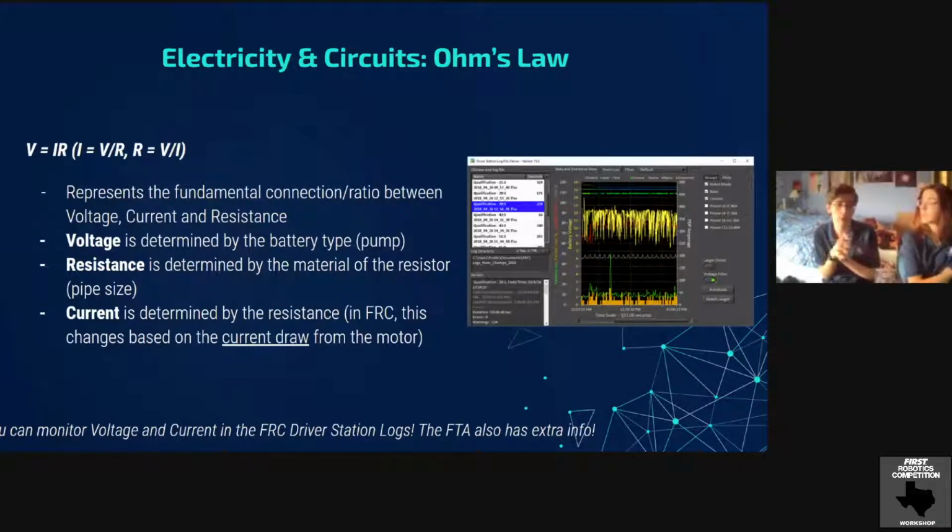Yeah, sometimes they don't even call it a brownout because they don't know what it was. Our robot died on the field. A robot died, or it started moving really slow and jittery. And if I hear slow and jittery, I know what it is immediately. And I pull up these logs. I will then go and talk to the FTA for them, or I'll take one of them with me to show them what I'm doing.